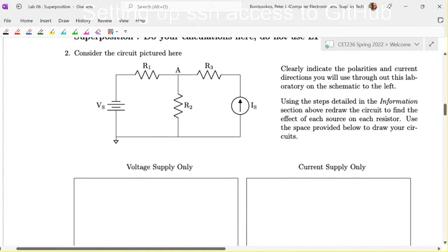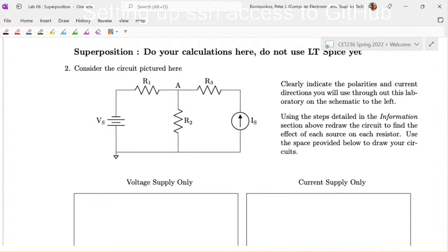Okay? So what I think the best approach to this is going to be to get your three resistors, measure the three resistors, then do your analysis on the three resistors with the known values. Then you'll be able to tell what the voltage has to be for the full circuit and what the voltage to represent IS has to be for the replacing Vs with its ideal circuit. Okay, does that sort of make sense?